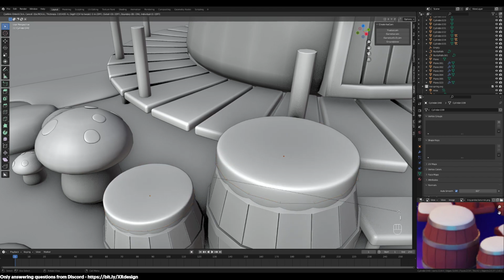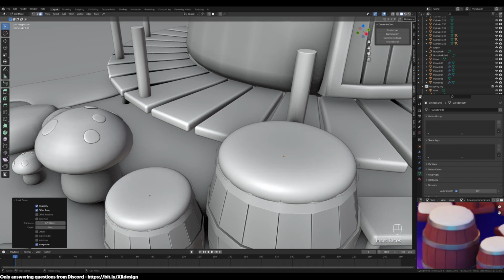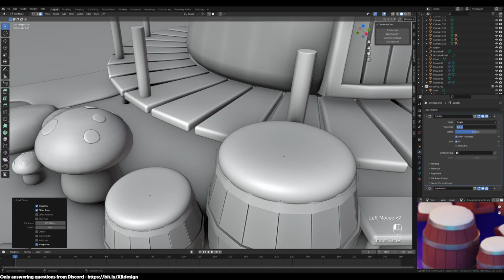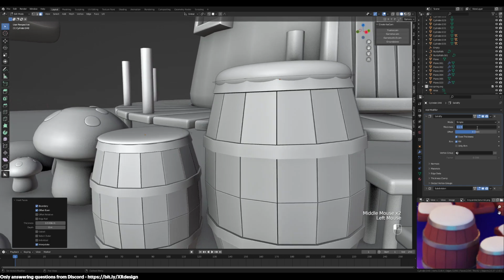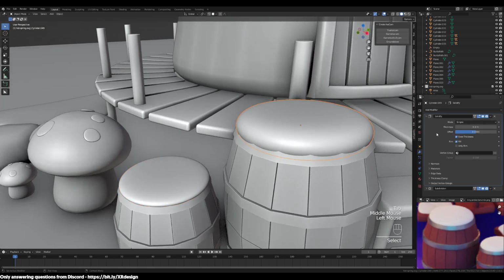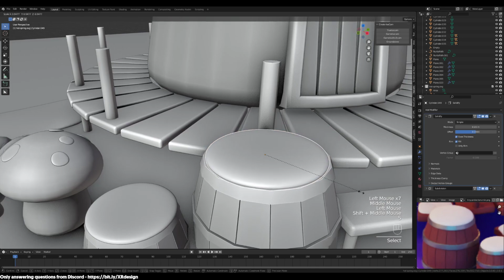And let's inset it slightly so it looks rounder. And then the thickness, we'll have to bring it back down to, let's say, 0.15. So just make sure you're doing that for both. And then if you wanted to change the scale, do that as well.